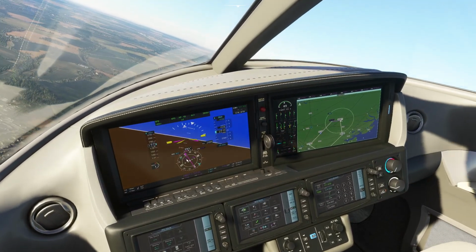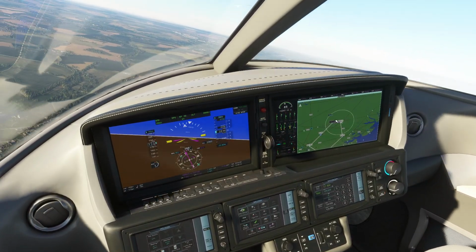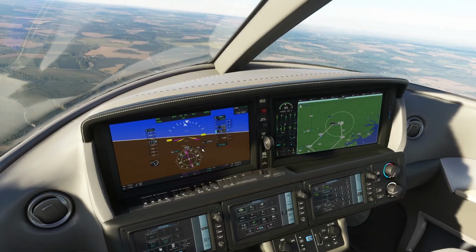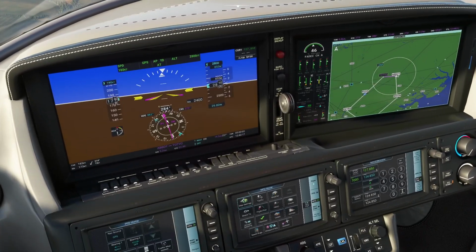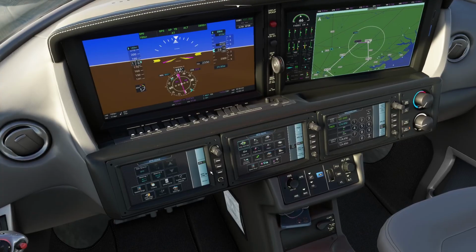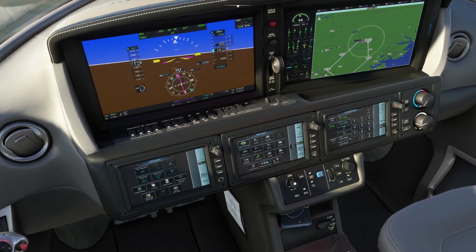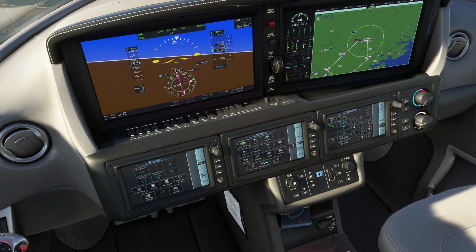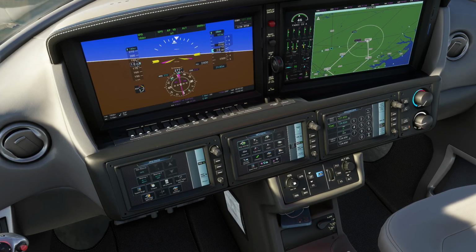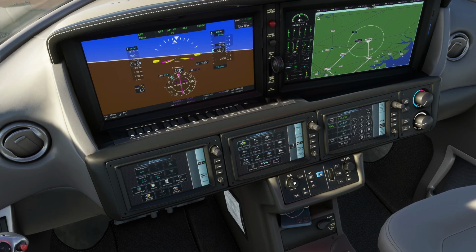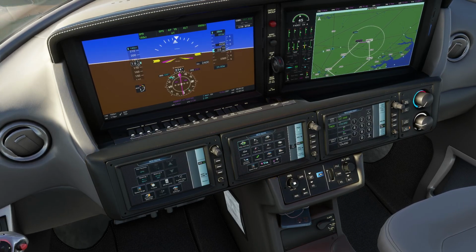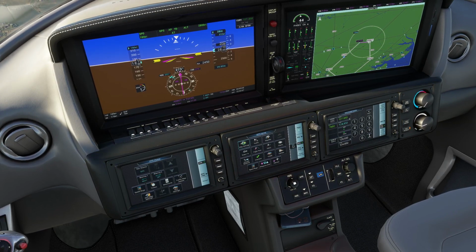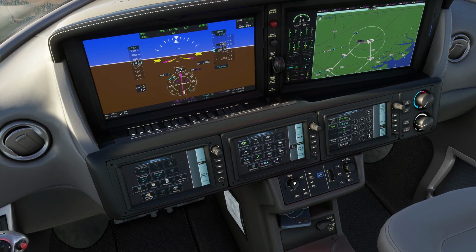Notice at the moment though it's just showing GPS. So when we come through Top Vo, we'll switch away from GPS, but we'll get our heading bug ready for nav mode on the way out of there. So we're kind of using all of the facilities available to us to allow us to change modes and do what we want without any surprises. So we're staying one step ahead of the aeroplane if we possibly can. So 2 degrees. Okay.